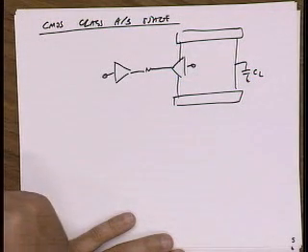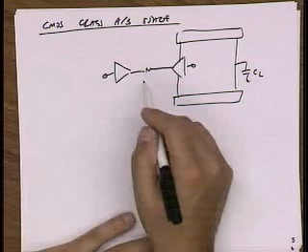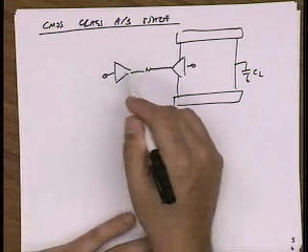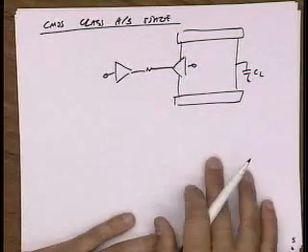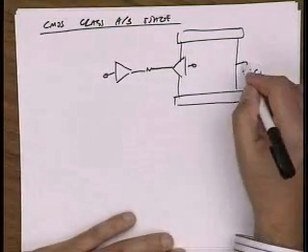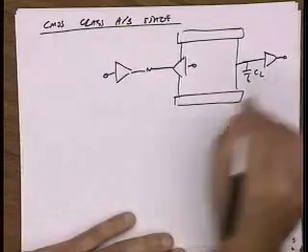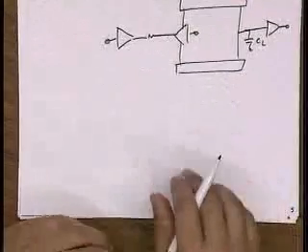And then at some point we thought, well, if we get rid of this second buffer stage, we get a current feedback amplifier. If we keep it, we get a traditional voltage feedback amplifier. If you're driving a resistive load, you include a buffer. Otherwise, you don't include a buffer.